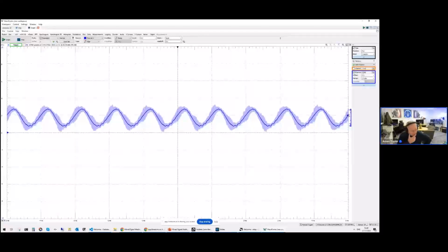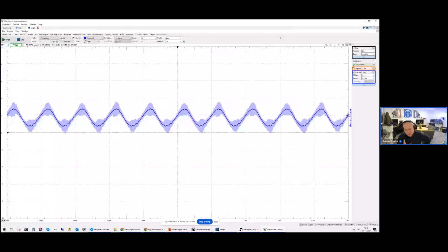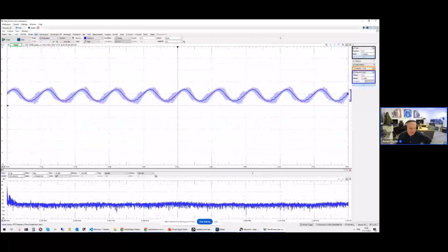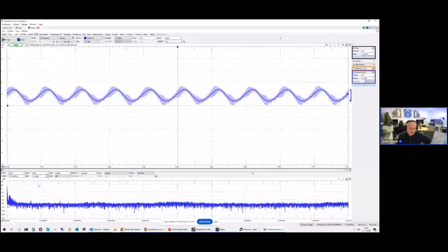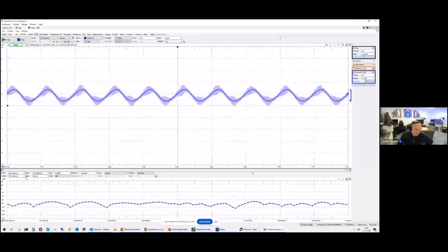It was actually a lot more difficult to get the PWM to give us a nice sine wave than it was the delta sigma, as you will see in a minute. So this has actually got a two-stage RC filter on the output, not a single stage RC filter. And if we do an FFT of this, we certainly don't want a span of megahertz.